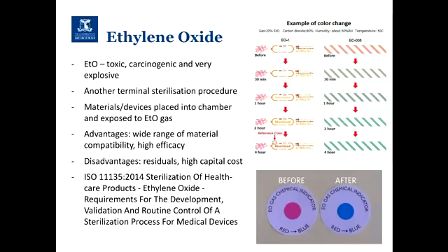When I used to test polymer discs, I used to get them sterilised by ethylene oxide. Gamma would have deteriorated the polymer, and as you'll see with steam, it also would have melted the polymer. Once it had been sterilised with ethylene oxide gas, I needed to leave it for 7 days before I was able to use it, to make sure the residue had dissipated and it was no longer harmful. How long you need to leave it depends on the dose, but most places that do ethylene oxide treatment take it somewhere for the gas to dissipate before they release it.